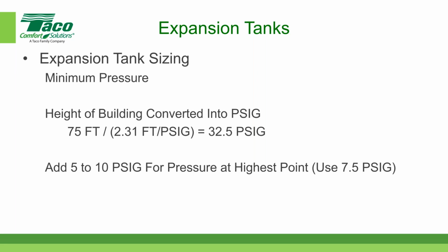And the second reason is that we do want to have some pressure at the top of the building to ensure that if we have any equipment at the top of the building, for example, a pump, especially in hot water systems, we don't run into the issue of having cavitation as a function of net positive suction head. NPSH, or net positive suction head, is really set aside for another discussion in the future. But the important thing is that we do want to have pressure at the top of the building.